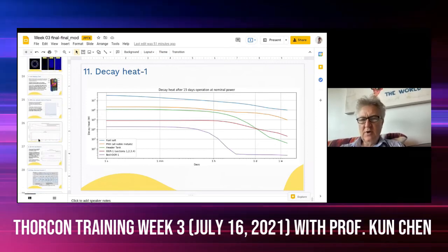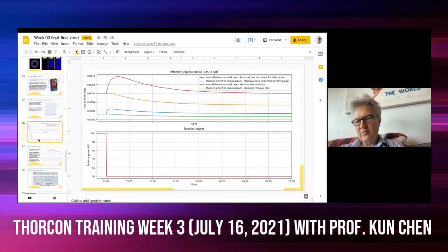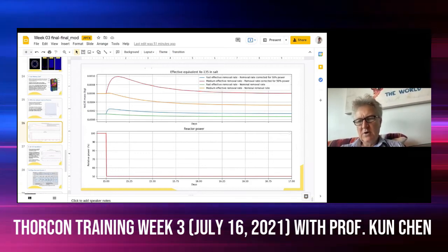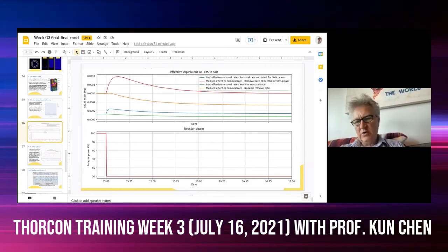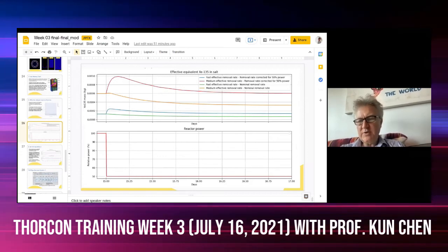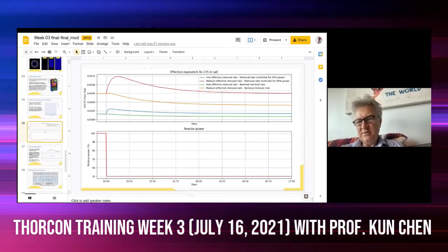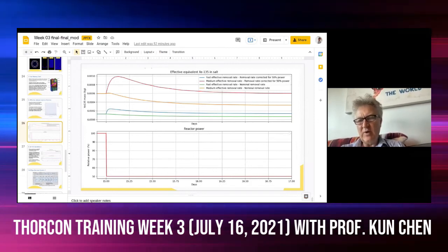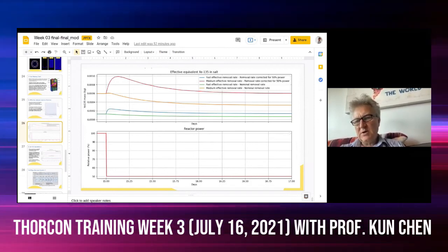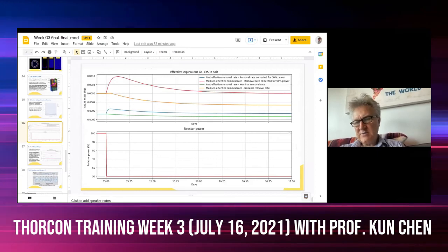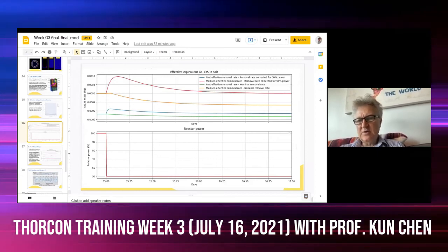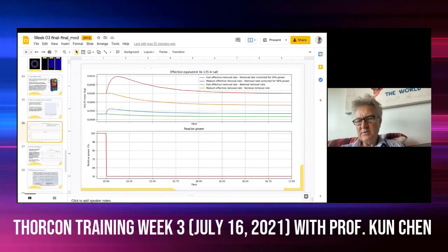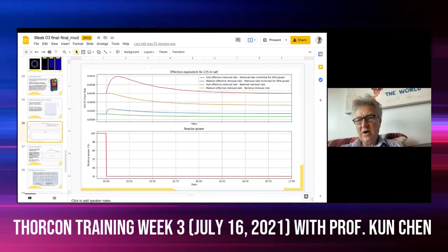So that's a big concern for a water reactor, that you have a negative void coefficient. We're a salt reactor. We don't get boiling of the salt. We have 700 degrees C margin. That is not something that will ever happen. So our bubbles are gas bubbles. There is no positive feedback system that's going to make more gas bubbles because it's getting hotter.